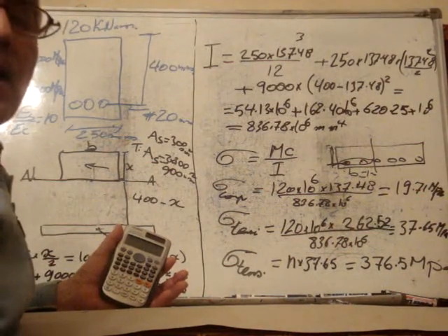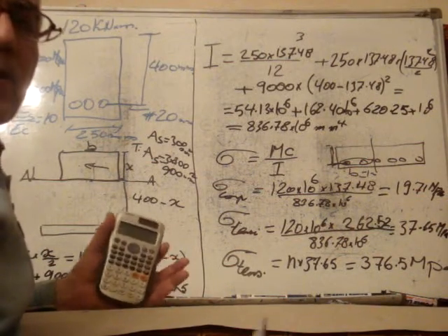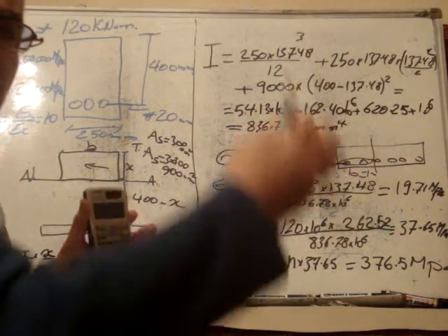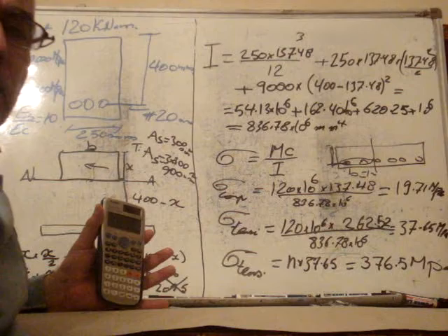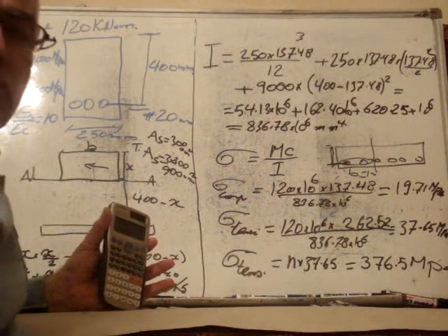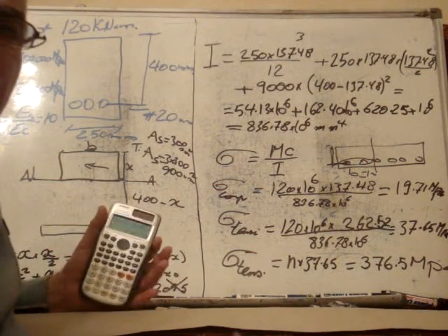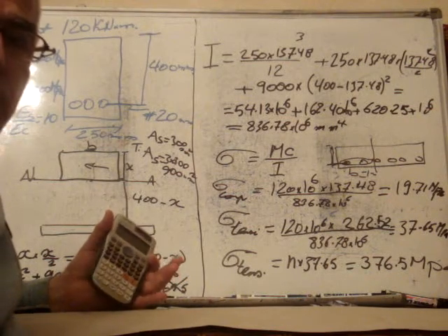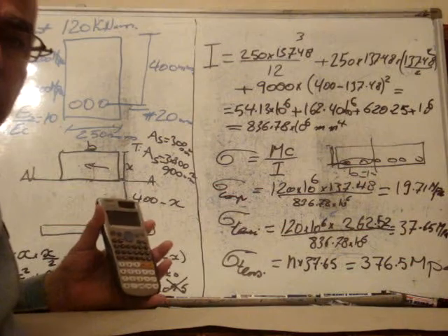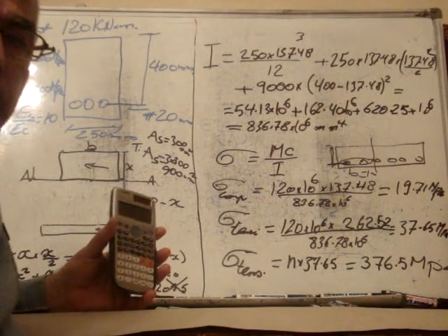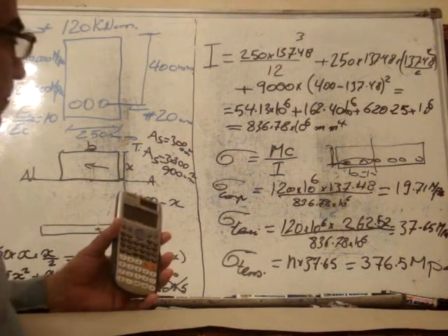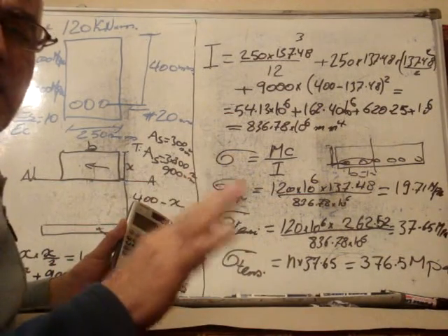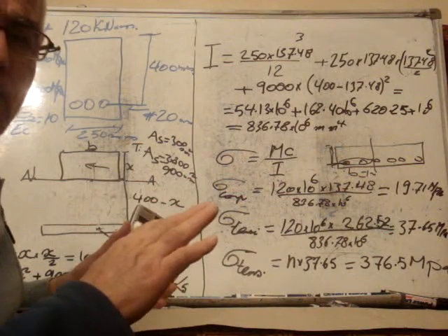In case I have imperial units, I take 1 foot, see how many bars I have in 1 foot, and assume the width of my section equal to 1 foot, and in this case I can calculate the capacity in 1 meter or in 1 foot, depending on what unit I am using. It is exactly the same way whether it is a slab or a beam.